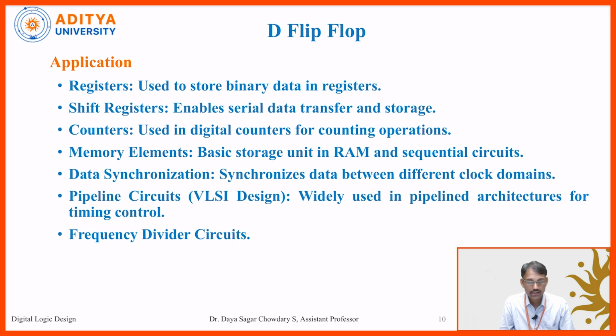And coming to applications, they are used in registers and shift registers. Used in registers means most of the time we have to store the data, and for that reason we use D flip-flops in registers. In shift registers, most of the time we have to shift the data, be it 4-bit, 8-bit or 16-bit data, according to the requirements of processors, RAM or ROM. There we use D flip-flops to store, and at the same time shift, this data. Counters also use D flip-flops, because we need to count and we need to store the data. For that reason these D flip-flops are mostly used in counters.